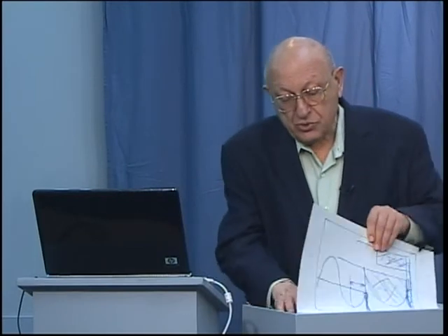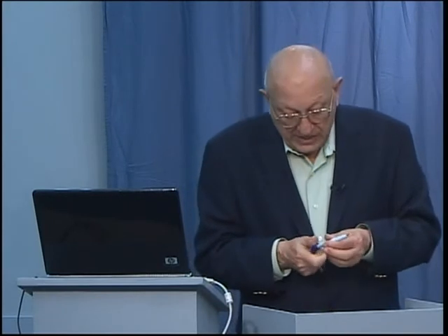Typically, we are used to a situation where if the same load is applied statically, it's probably better than if it's applied dynamically. And that's true. Let me show you a classical, well-known situation, where we often talk about the dynamic factor. What does dynamic factor mean? It means: what is the maximum displacement, the maximum stress in the linear system if the same force is applied dynamically rather than statically?